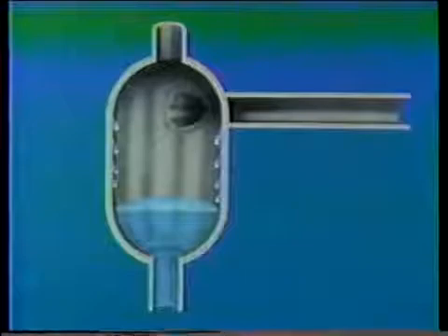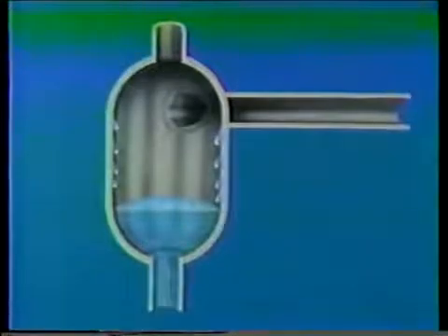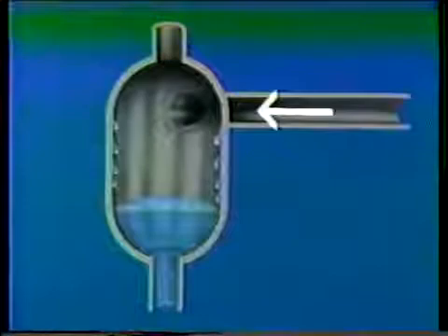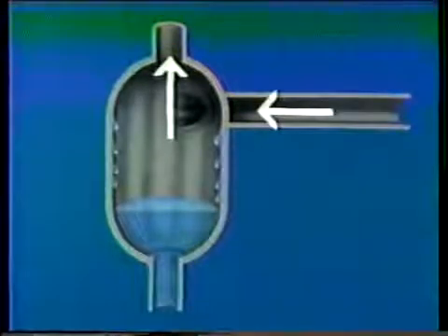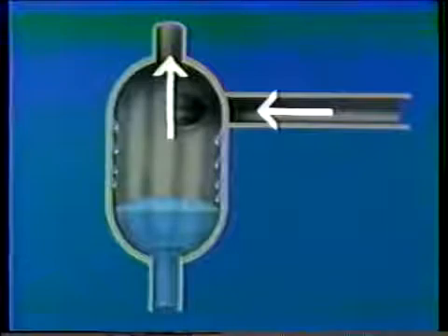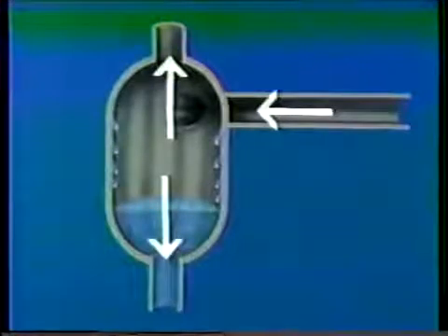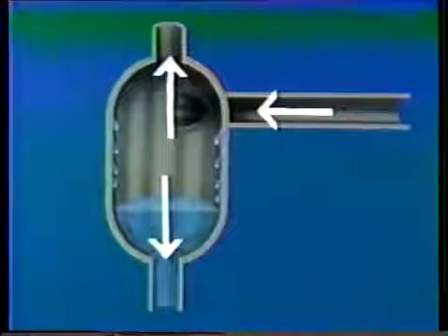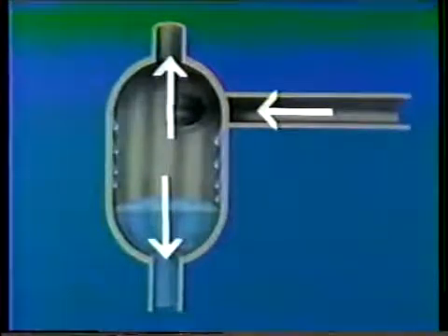Well, so far we've been referring to a drum-type boiler. A once-through type boiler has some specific problems besides the ones common to both boilers. A once-through boiler has no drum, but it does have a moisture separator. The moisture separator of a once-through boiler has 3 large pipes attached to it: the wet steam inlet, the dry steam outlet, and the water outlet. All 3 should be inspected for cracking and evidence of corrosion or erosion.